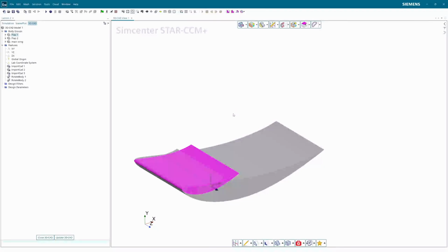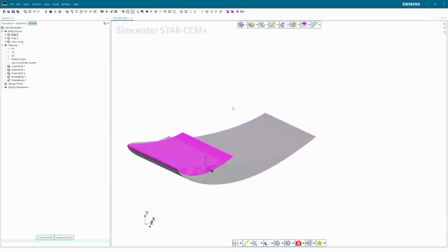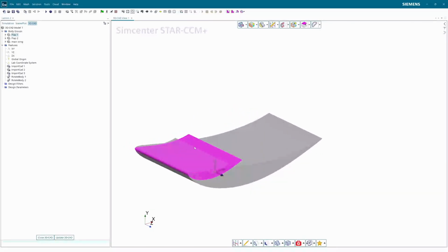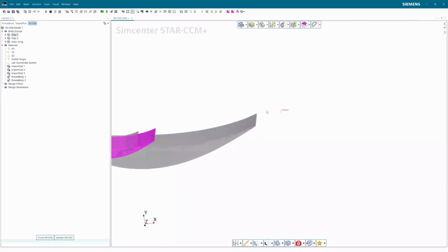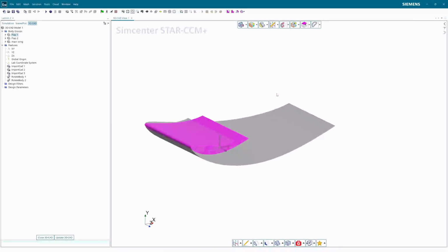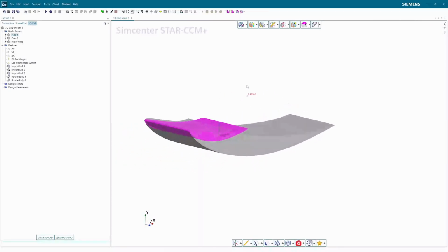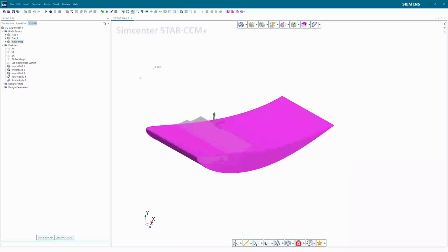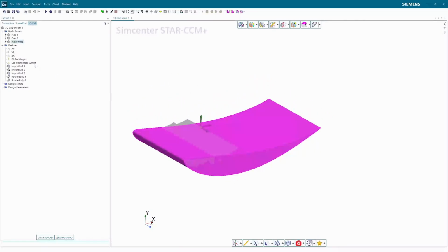In general, when you want the small parts, for example these flaps, you want them always to follow the trailing edge of the previous part. So it's always better to first do the transformations on the main part. Right now, the first thing that we will need to do is add an angle of attack transformation on our main wing. And so we will start by doing that.